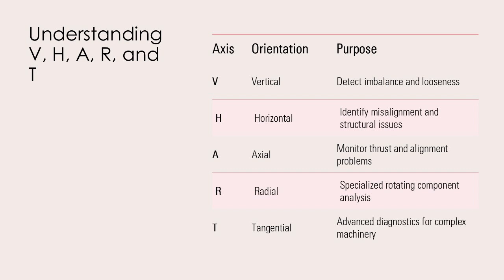Measuring along these axes helps identify issues like imbalance, misalignment, and looseness, which may manifest differently depending on direction. Comprehensive analysis requires data from all relevant axes to ensure accurate fault diagnosis and prevent overlooking critical vibration patterns.